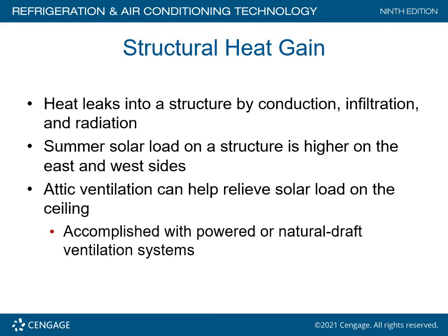Structural heat gain, very important subject here. Heat leaks into a structure by conduction, infiltration, and radiation. Summer solar load on a structure is higher on the east and the west sides of the buildings. I know this very, very well. Attic ventilation can help relieve the solar load on the ceiling. It's accomplished with powered or natural draft ventilation systems.